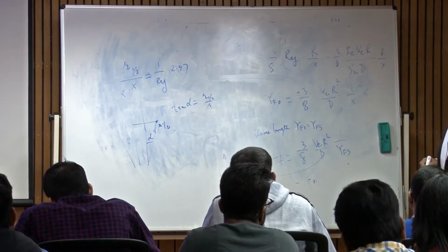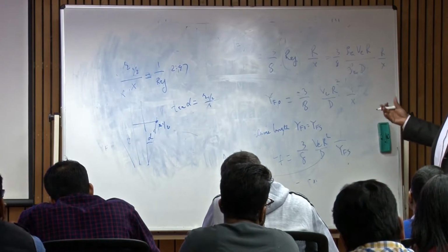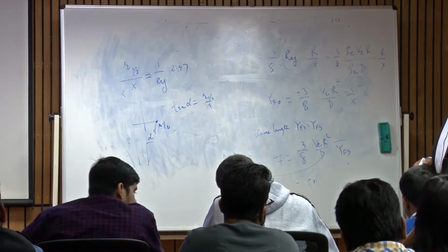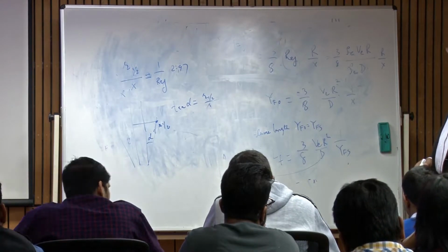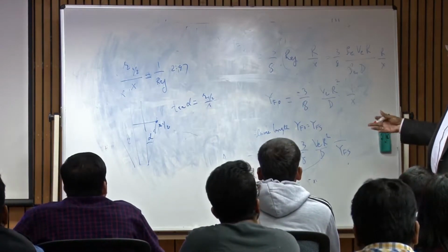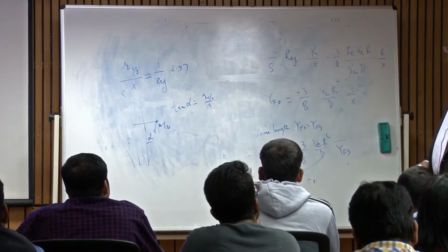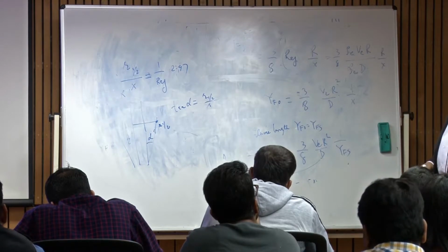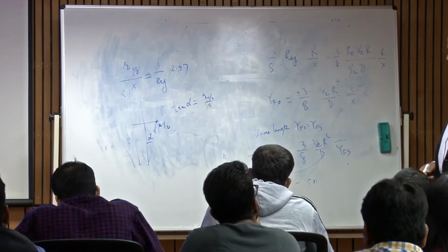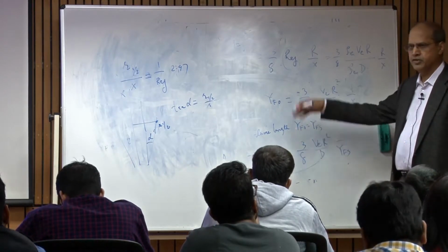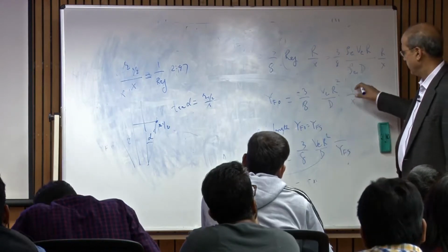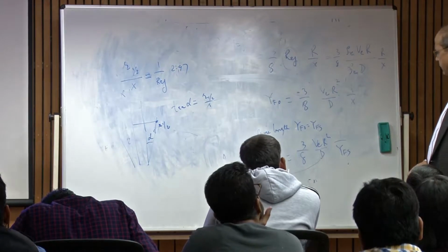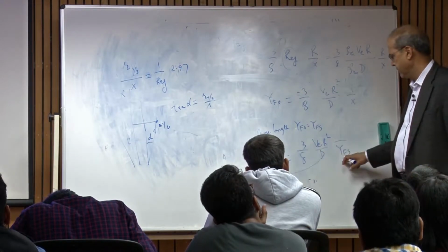So this is the benefit of this non-reacting, constant density jet solution. It gives us the distribution of YF, which may not be totally realistic, but it gives the qualitative distribution. That is, YF value is decreasing along the center line. In this particular case, it decreases as 1 over x. And from there, we can extract the flame length.